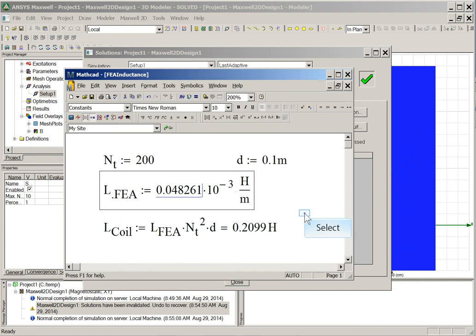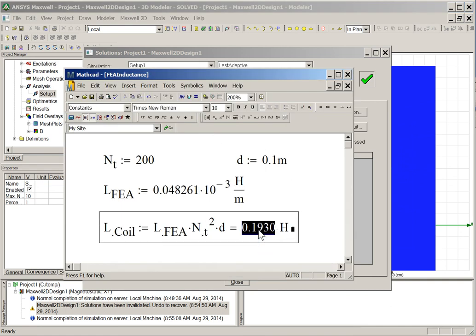So my result now is 193 millihenries, so it's a reduction. So saturation in a core either reduces the inductance, or if there isn't any effective saturation, it'll keep it the same. You'll see a lot more of the features in Maxwell when you do the second lab, but this is just an illustration to show you how it can improve the accuracy over textbook calculations.